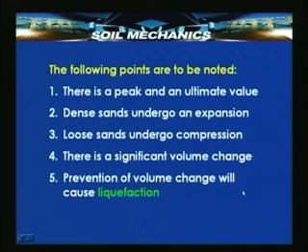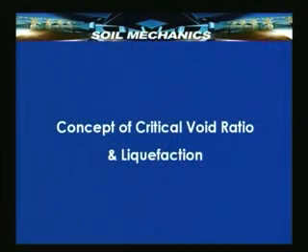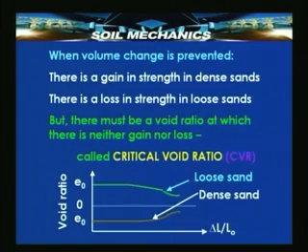Prevention of this volume change is not going to permit development of the effective stresses and the friction angle, and therefore it will lead to a kind of failure which arises because the soil now behaves like a liquid. Shear resistance is not allowed to develop due to volume change prevention, and this phenomenon is known as liquefaction. Now, let us take a look at the concept of critical void ratio and the meaning of liquefaction, the significance of liquefaction, and how to determine it.